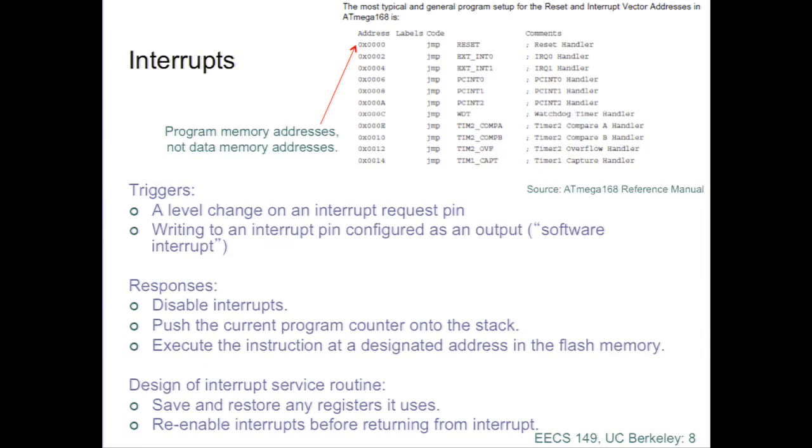Typically, it gets put on the stack. So now, how is all this done? Is it hardwired that if there's an interrupt, you take this and put it in a dedicated location, which would mean that in the stack you need to have one location reserved for putting the address when a hardware interrupt is triggered? You don't have to pre-reserve it, right? The whole notion of a stack is that the stack pointer is pointing to your next available location or your last filled location, right? So it unambiguously defines an available location. Which means that as there is a trigger, the hardware first looks at the stack pointer, and onto that location it transfers the contents of the PC.